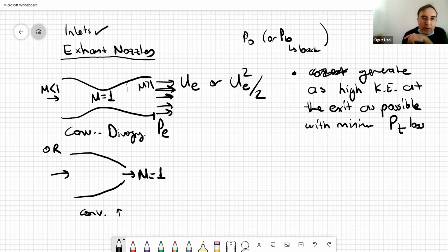This nozzle exit is going faster than the speed of sound if it's supersonic, yes. The back pressure information is propagating here with M equal to 1. This wave cannot reach here. So this does not know what the back pressure is. So it becomes independent of back pressure. So this means that it can be bigger or smaller than back pressure, which resulted in different operational modes we discussed, if you remember, and I will draw it again. This under-expanded nozzle, over-expanded nozzle, things like that. That's for supersonic exit nozzle speed. Yes, nozzle Mach number. If it's subsonic, there's no such thing as over or under-expanded. It's irrelevant because it's always equal. Yes, we discussed this. Anyway, I will come back to this point in a second.